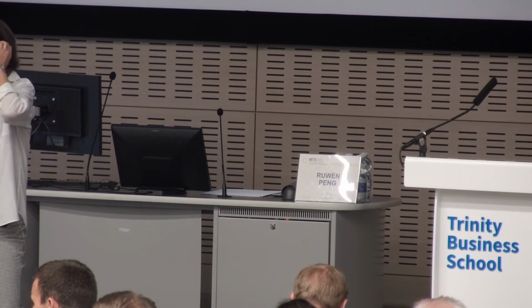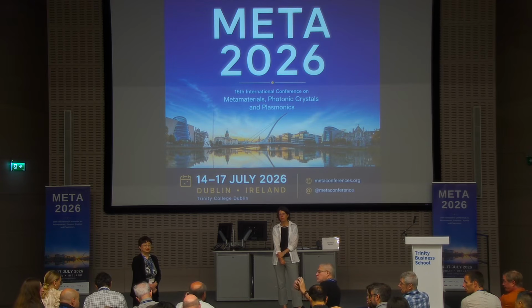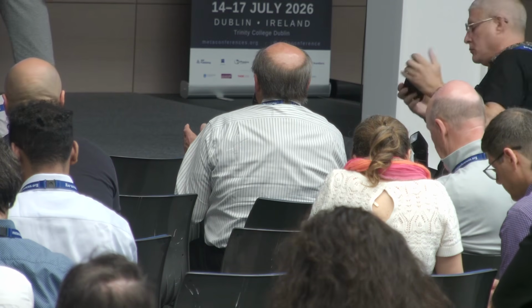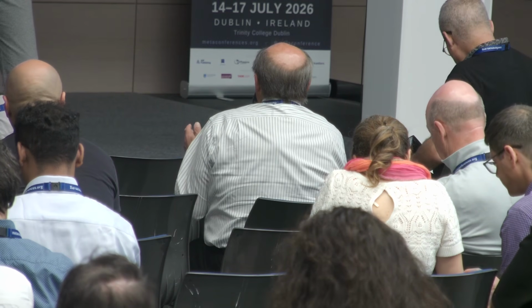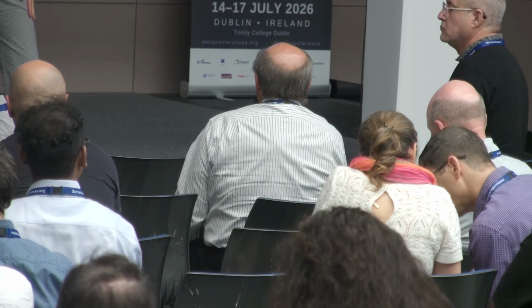I had a quick question, just of interest. Very nice work. What is the insertion loss of these sol gel structures? Because the on-chip propagation lengths and also the sidewall roughness are killers in most of the materials on chip. For sure, the insertion loss. Whereas lithium niobate is known to be the lowest loss material for nonlinear optics.